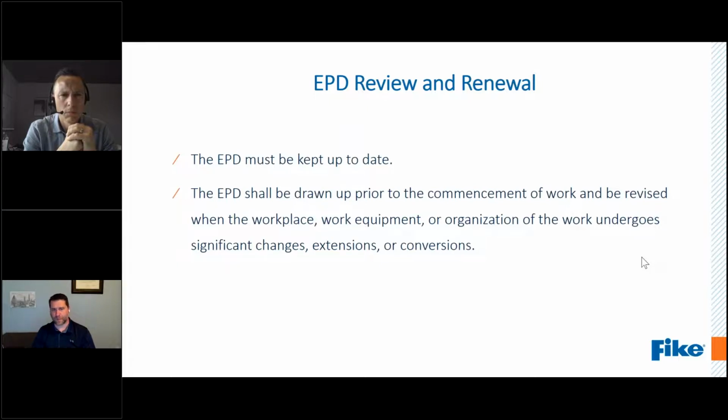If you're starting up a new facility, you're generating this document as construction is going on, so that it's in place prior to starting operations. If you're going to add new equipment, you're updating this as you're adding that equipment. It is in place, and everyone's trained on the procedures and the hazards prior to starting up. And then you should do a periodic renewal or revalidation. I think most companies tend to do them on a 5-year basis.